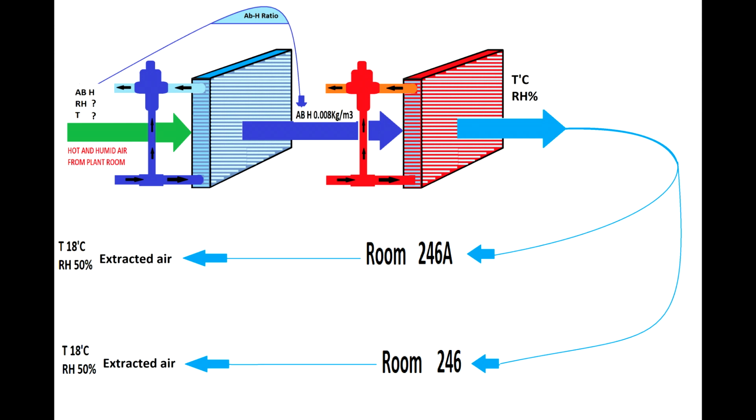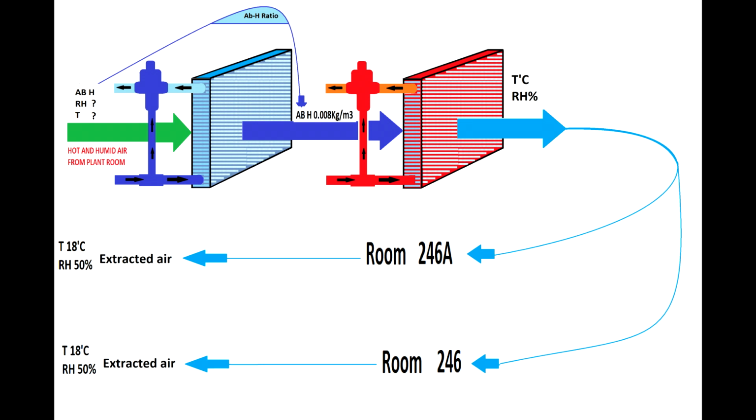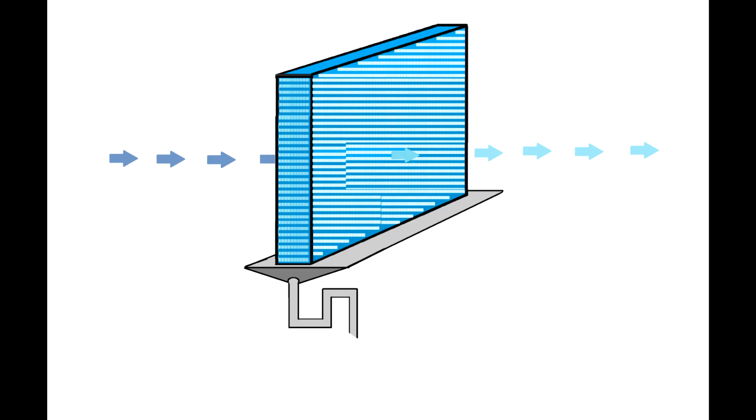If we have a bigger quantity of air, or if the heat exchanger is not cold enough because of the glycol temperature or glycol flow, or maybe it's too much air for the heat exchanger, then you will not remove any moisture from the air, and then the process will be very bad. So this is about a short video, and now I want you to continue to watch this video to see that there will be an impact if we have incorrect air change rates, and I want you to look at the calibration.